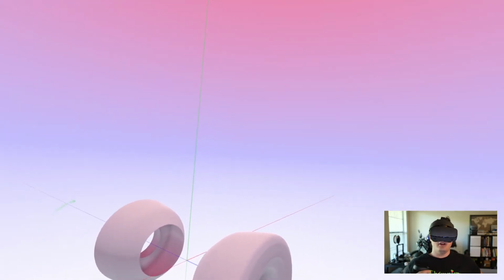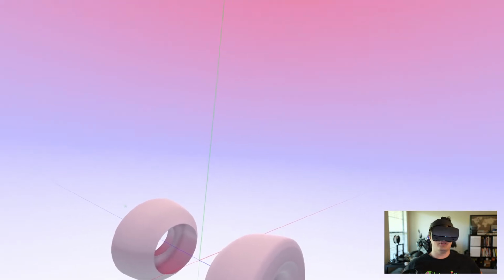Is there a way to accurately resize the mannequin reference models to, for example, 180 centimeters tall as opposed to the default 170? Then have this as a saved default. There's not really a function for that, but there are ways to do it. The solution to this type of thing, to defaults and presets, is saving sketches with these things in them, and then opening those sketches, and once you've used them for what you want, saving them as a different name so it's a new sketch.